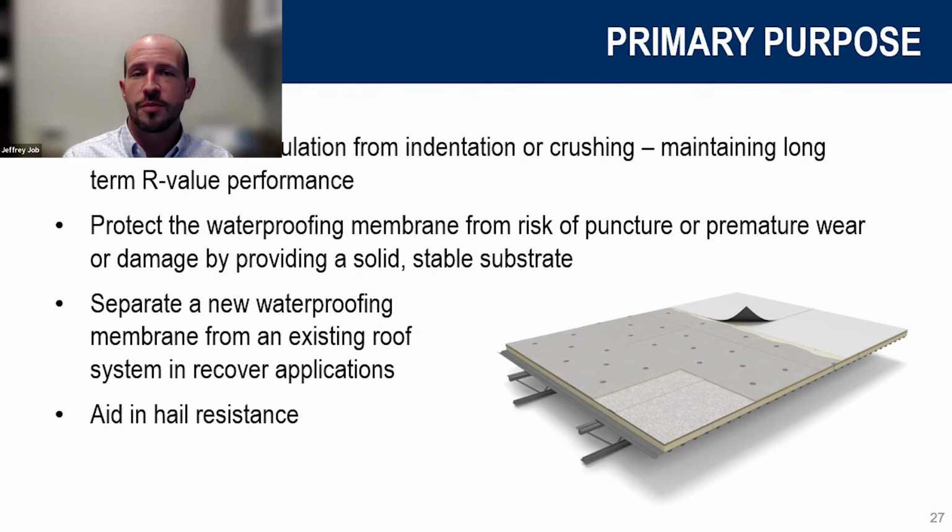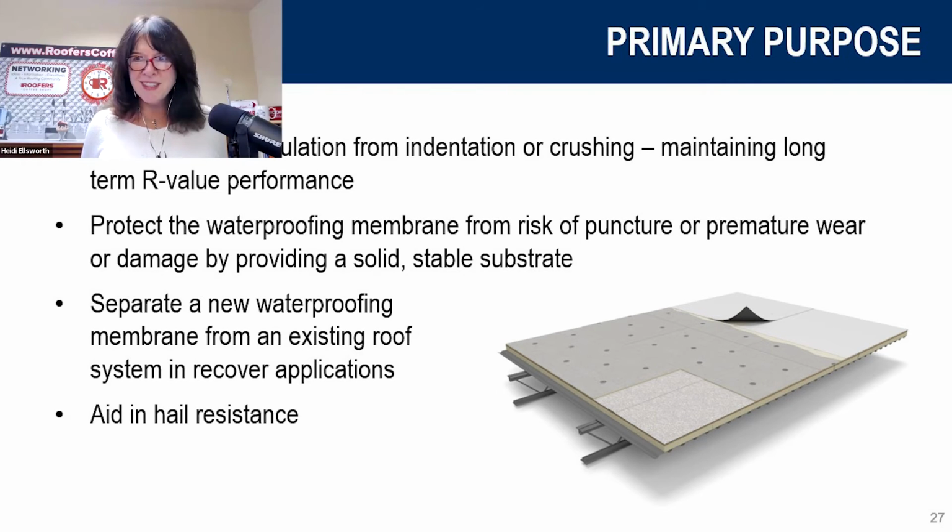Overburden protection, for example, ballasted systems, things like that, you're certainly going to want additional compressive protection in there to help support the insulation below, as well as the membrane. If you've got a hail ball impacting it and it doesn't have anything below it to support it, then there's potentially more damage on that membrane, versus if it's got a nice, hard, robust surface to resist that impact. That's great from the membrane perspective. Then you get a bounce.